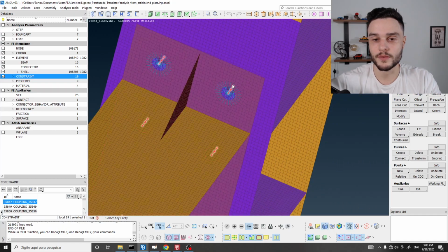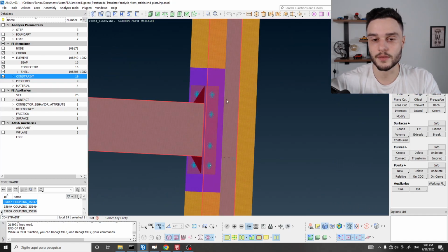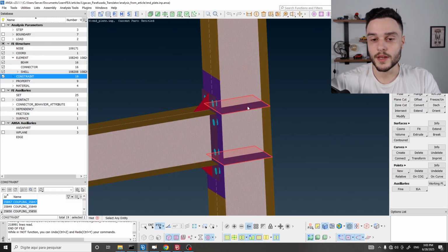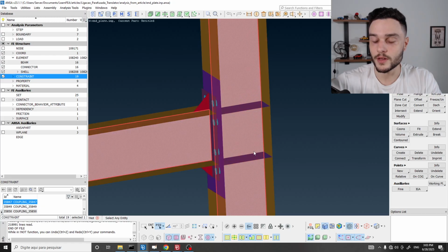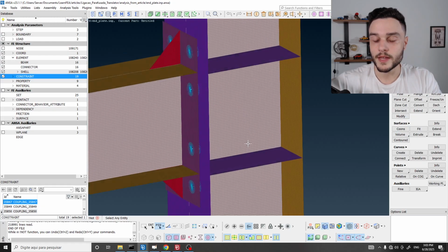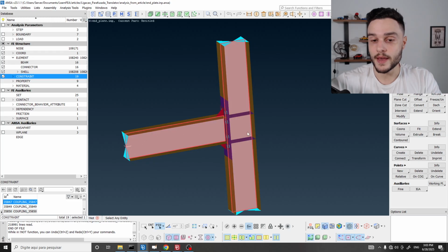You see, we have these holes here. In this case, I have 8 holes. And then we are going to have a bolt passing through these holes. We can have stiffeners in the column as well. Actually, for this type of connection, we should have these stiffeners at the columns in the same height of the flange of the beam. And in that way, we are going to have the behavior that is expected for this type of connection. Okay.